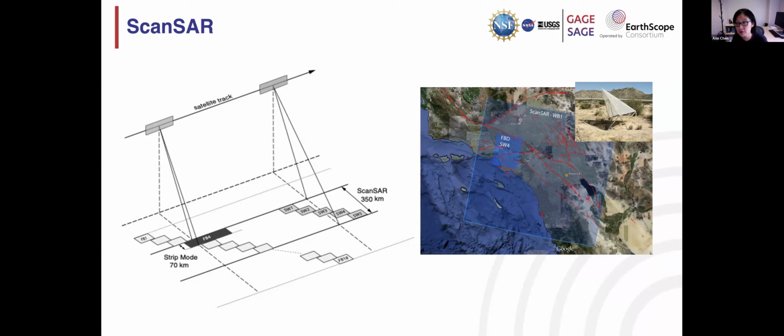And of course, this process has a trade-off. For the Stripmap mode, we use all the pulses to form the image, so you can think of it as the entire synthetic aperture length. But when you divide all those pulses into 5 separate chunks, equivalently, the synthetic aperture length drops to 1/5. The sacrifice is reduced azimuth resolution.